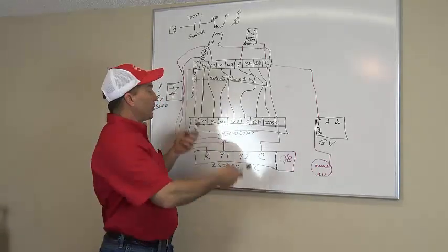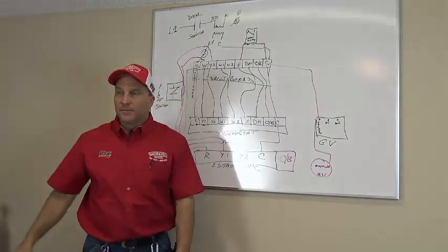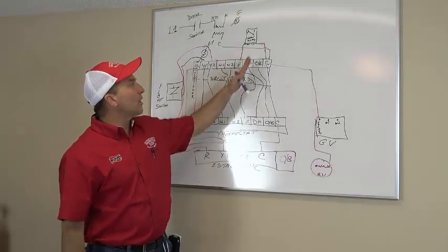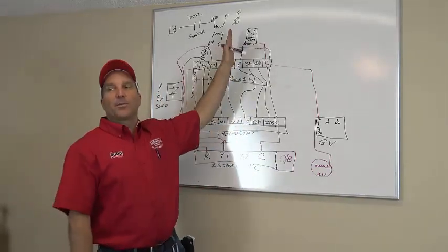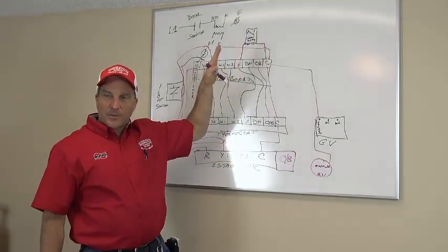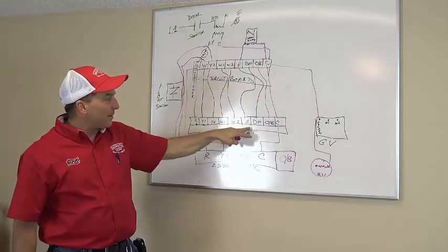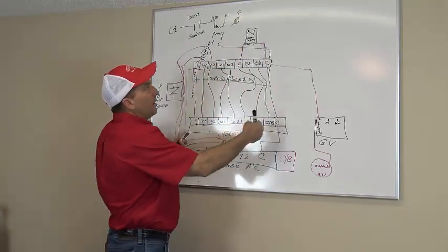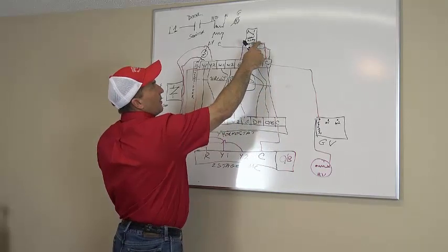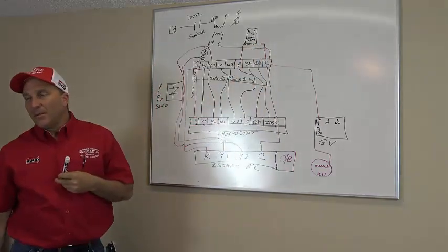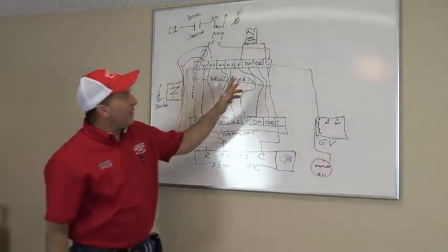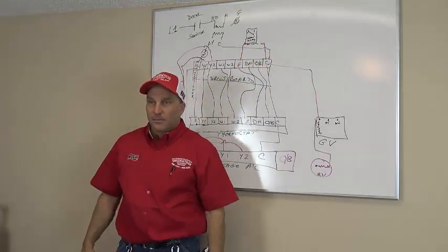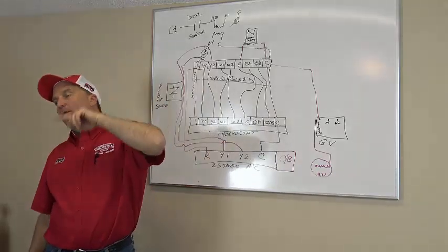You want to know why your fan's not coming on? You can tell right there at your thermostat by going R and G, right? There's no voltage. That tells me there's a broken line somewhere. That doesn't tell me there's a broken coil. It tells me there's a broken line not bringing power back to my G. So if I go R to G, that could mean this ain't there, right? It could mean anything. It can mean any of the wiring going from here to here all the way through is something's not connected. Because it didn't follow all the way through the common.